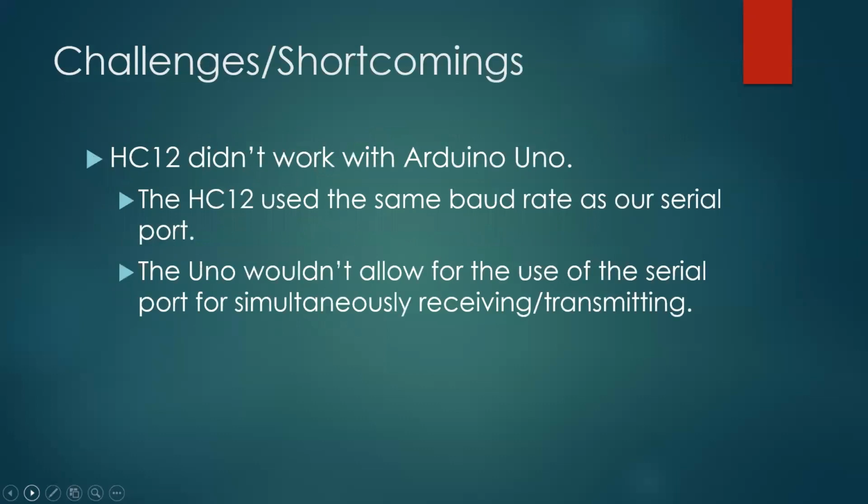Some of the challenges and shortcomings we faced, definitely the HC12 was a big challenge, considering it didn't work with the Arduino Uno because it used the same baud rate as our serial port, and the Arduino Uno does not allow for the use of the serial port to read and write, or in this case, simultaneously receive and transmit.